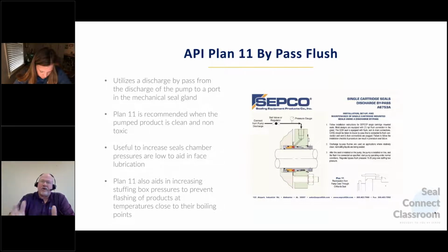If you had a water pump, for instance, and you ran it without a discharge bypass, the water around the seal face in the back of that stuffing box is going to be stagnant, and it's not going to flow through there and keep a cleaner, cooler fluid around it. You're just trapping the fluid in there, and you want that fluid to flow from around that seal face back into the pumpage and keep something cooler in there all the time, instead of trapping fluid back there.